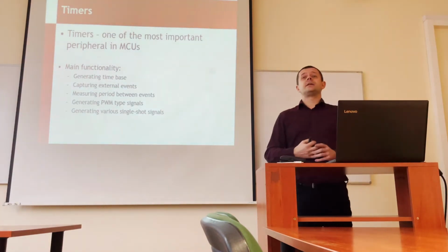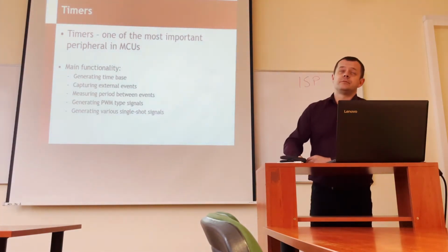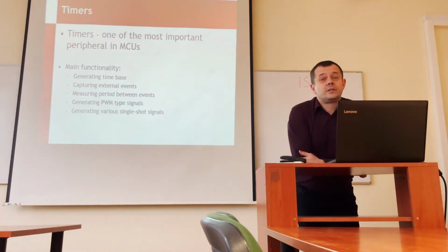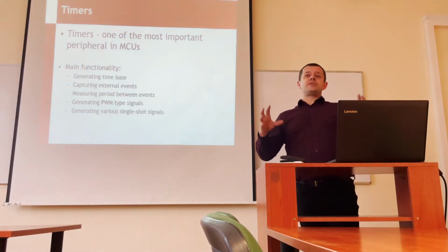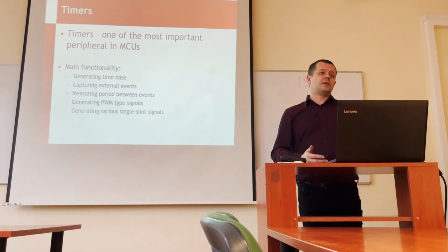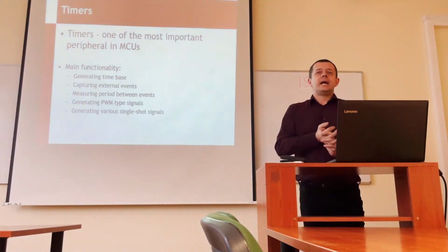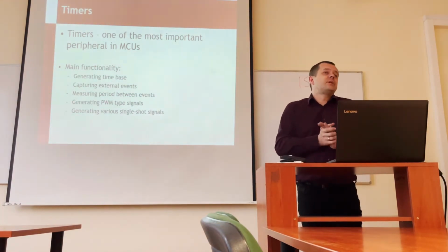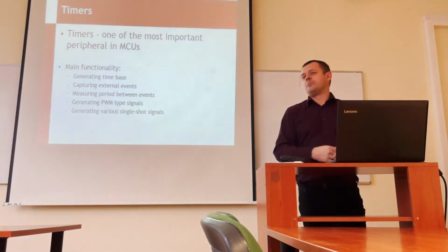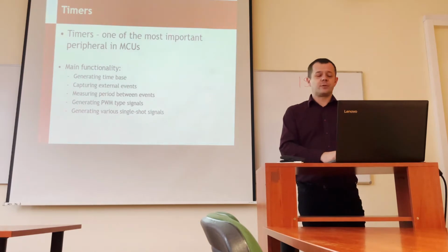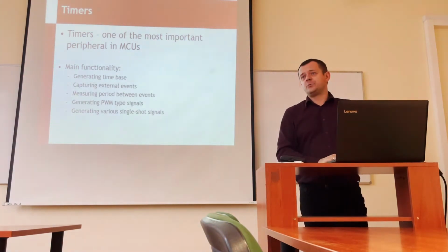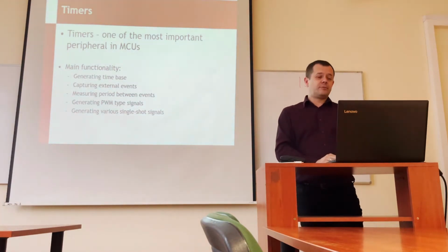Timers, something really simple. At least it used to be something that counts time. Naturally, we can use a microcontroller with ports to do this, because a microcontroller is clocked with a certain clocking speed, and we can do something in software to count, to monitor the inputs, to generate the output in a timely manner, to generate a time base.